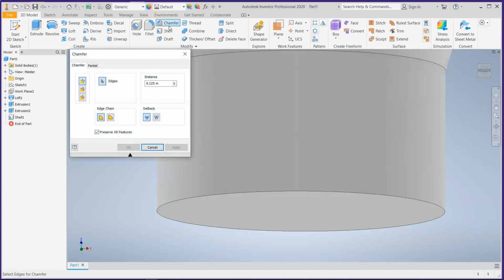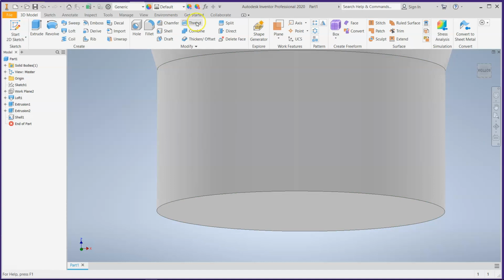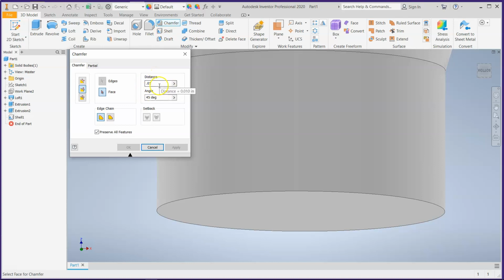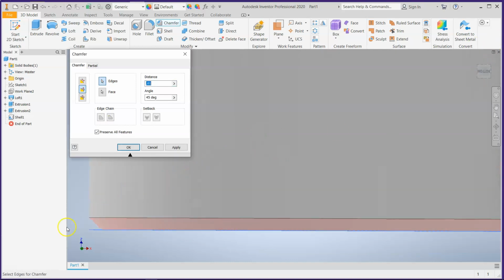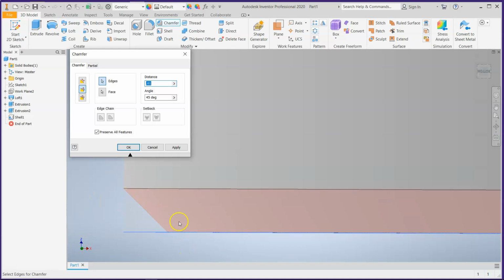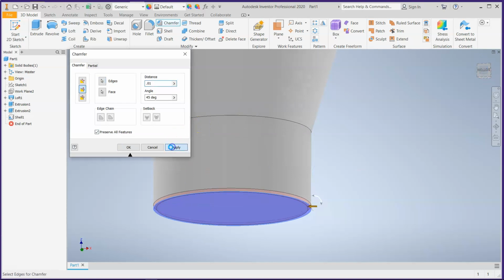So let's place a chamfer. And it had a distance and an angle measure. So that's the second button here. So our distance was 0.01, 45 degree angle measure. So we're going to click here. Cancel. Let's try it again. Oh, not shell. Chamfer. 0.01, 45. I'm trying to click here, this face, and then that edge. And so what that's done is that's given us this angle. So it makes it slide into the hole a little bit easier if you're thinking about real world application.